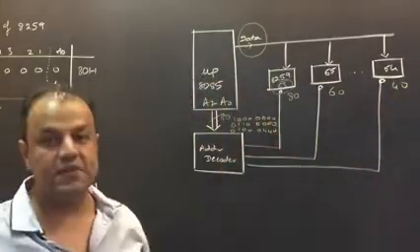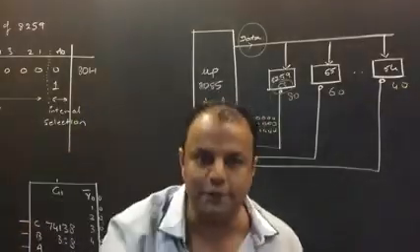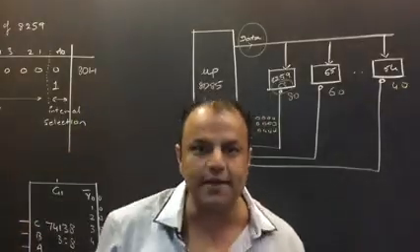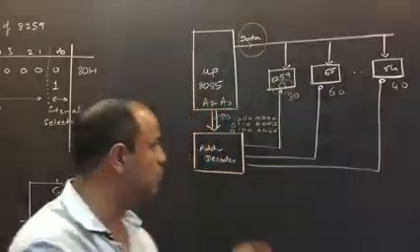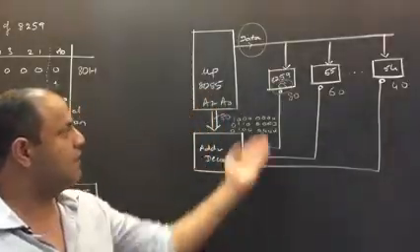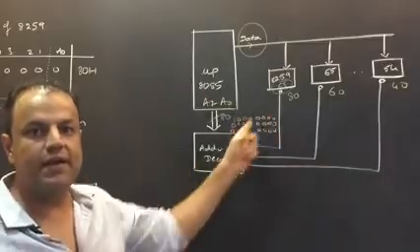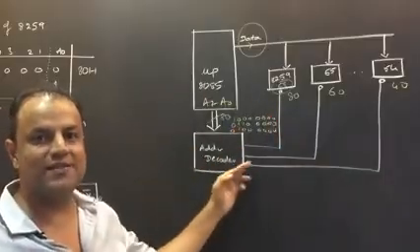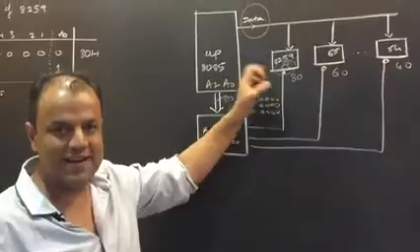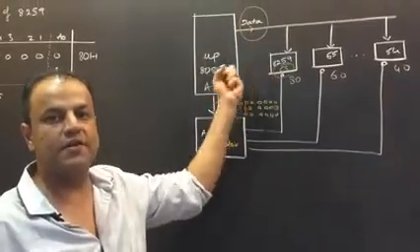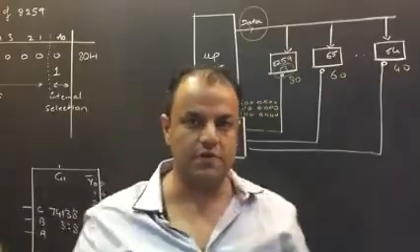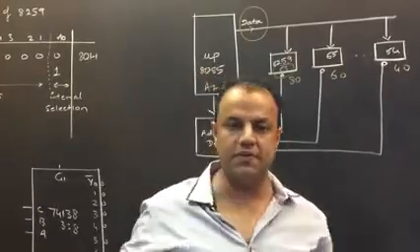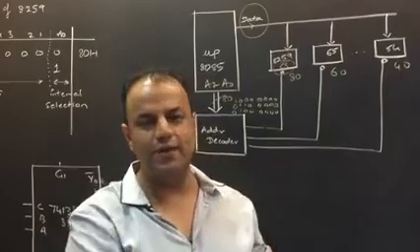This chip's address is 80, but for the rest of its life, it will never know that its address is 80. Who knows? The person who has done this designing, the person who has made the motherboard, has made a circuit that will select this chip when address 80 is issued. So whenever the processor issues the address 80, the chip gets selected, then the processor gives out read and write signals, and based on that, data is transferred. That is the idea. Are you clear? So the processor gives 80, 8259 will be selected, the processor gives 60, 8255 and so on.